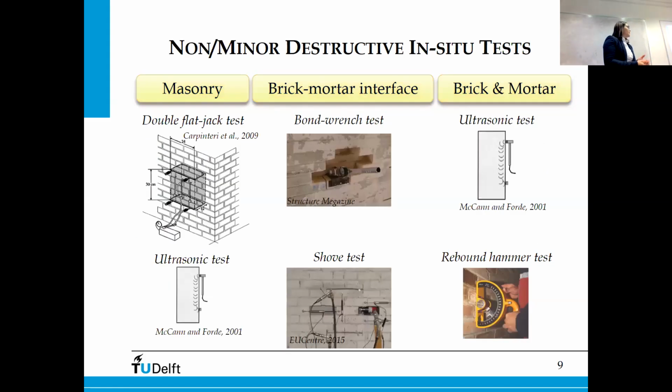And of course, there have been some developments for non- and minor-destructive tests to be used on site, starting from the philosophy of knocking on the brick with a rebound hammer or ultrasonic test, or doing something a bit more complex to try to obtain the property of the interface between brick and mortar, or even this flat jack type of test.